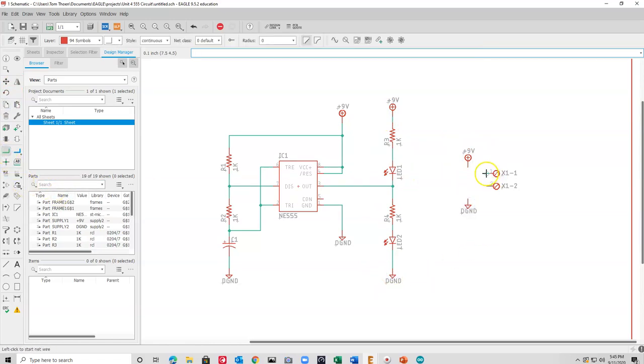And by the way, this is what I left off of the previous schematic, why you might have been getting an error. I'm going to connect those two terminals together. What that means is that the battery is external to the circuit board. But just like before, because we've got that connected to the 9-volt circuit, all the electrical connections are the same, even though you don't see a trace connecting there or the ground. All those are connected together.